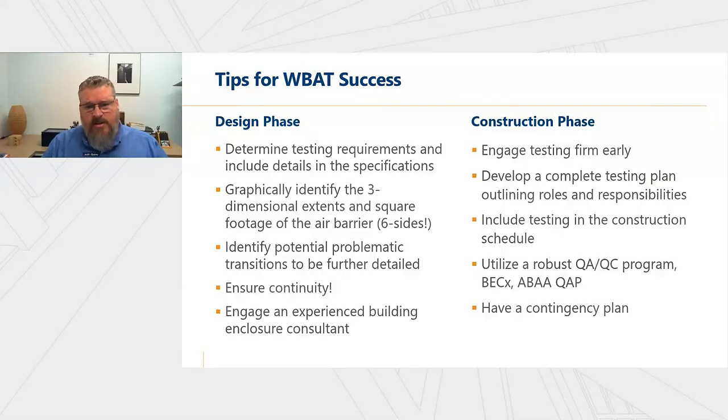During construction, you utilize a robust QA/QC program for the air barrier systems. That can be included as part of the building enclosure consulting. ABA, the Air Barrier Association of America, also has a great quality assurance plan that can help with that. And then have a contingency plan for testing.